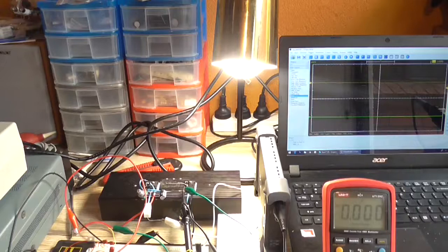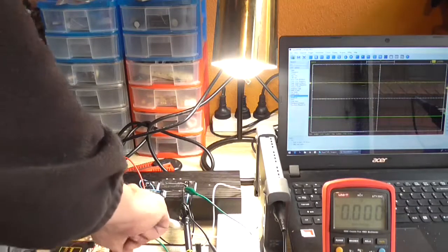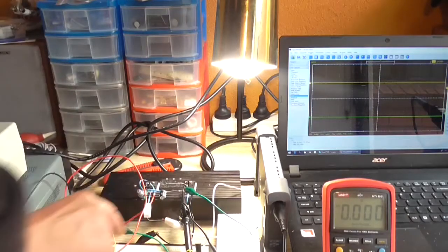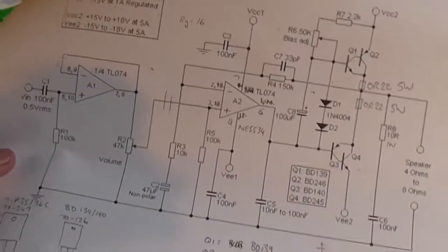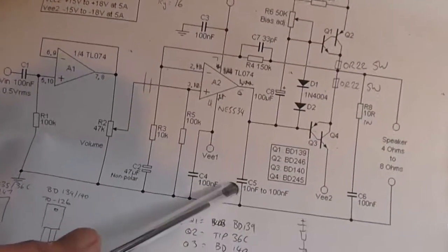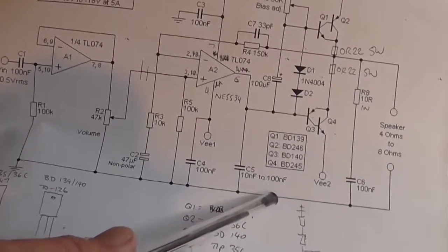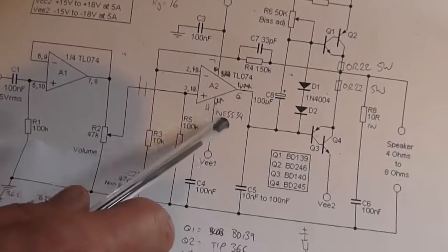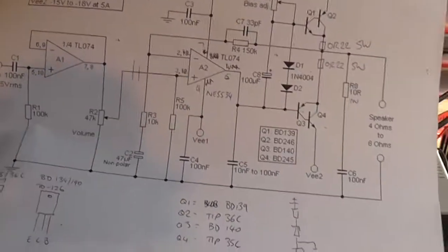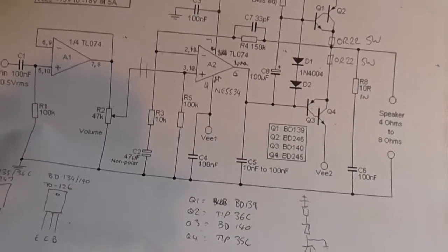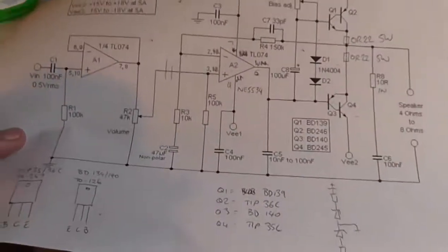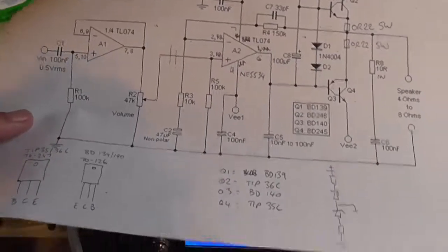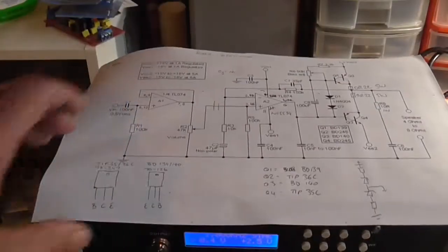So I'm going to disconnect the output stage from the equation here and just have a look at what our voltages are, because I might have one of the things wired incorrectly here. Well, I figured out what was causing it to oscillate: this capacitor C5 here, which was originally 100 nanofarad in my circuit, was causing the entire thing to oscillate, and it was drawing over 3 amps of current out of the power supply, even with a 100 millivolt peak-to-peak input. So yeah, I took that capacitor out completely.